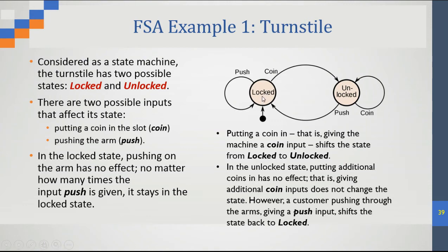If you push the arms but you do not put the coins, you will stay in the locked state. So we have two states: the first state is locked and the second one is unlocked or open. Once you push the arms, it will not open. So push is an input. Once you push but you do not insert the coins, it will not open, but you will stay in the locked state.